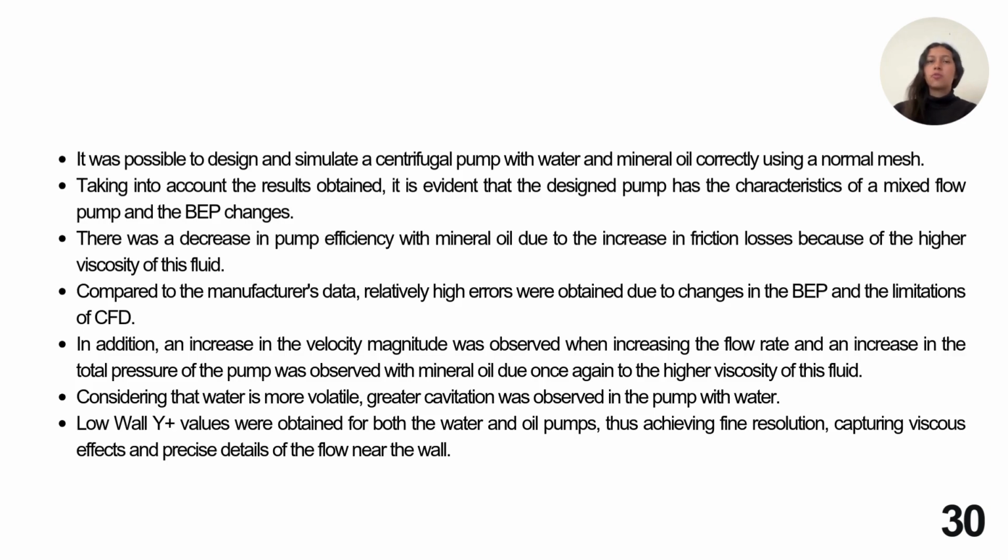In conclusion, it was possible to design and simulate a centrifugal pump with water and mineral oil correctly using a normal mesh. Taking into account the results obtained, it is evident that the designed pump has the characteristics of a mixed flow pump and the BEP changes. There was a decrease in pump efficiency with mineral oil due to its higher viscosity. Also, compared to the manufacturer's data, relatively high errors were obtained due to the change in the BEP and the limitations of the CFD.